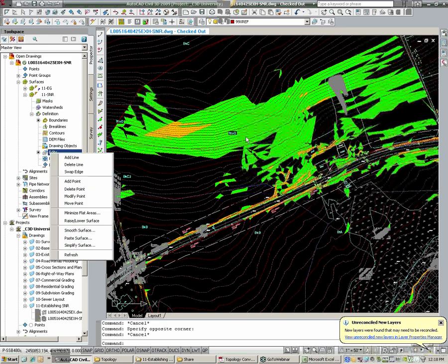If you do have a real surface that's made by actual survey, or from an aerial company, and whenever you are getting aerial from aerial companies, you should always be hitting the PMs, or if you are the PM or the engineer, to get the surface data, not just the contours. All aerial firms do their surfaces nowadays with computer modeling, so you need to get the DTM mass points and the break lines from them. They never send it right off the bat. You always have to go back and ask.